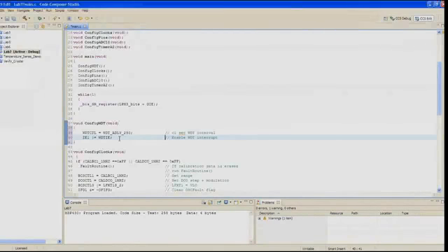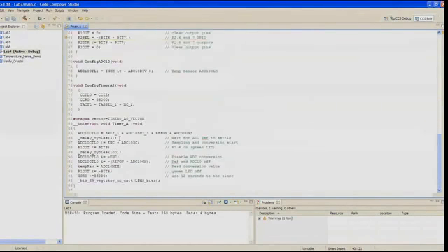In step 5, the code in the timer A0 ISR now needs to run when the watchdog timer triggers. So change the top portion from the timer A0 vector to the watchdog timer vector, WDT vector, at the top, as shown in the steps in the book.